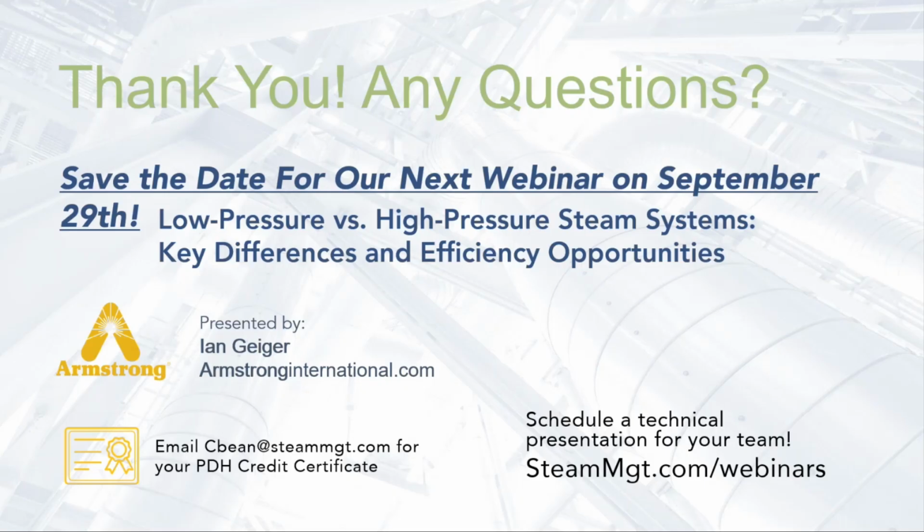We don't have a lot of use of them outside of steam systems, because the most value comes from these types of units when they're paired with the rest of a wireless infrastructure. So monitoring 3 or 4 pressure relief valves that are not on a steam system might not be economically viable. It's typically when customers are monitoring 50 steam traps and they want to monitor their pressure relief valves on their steam system. So that's usually where they utilize that.